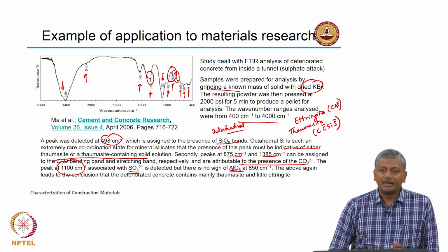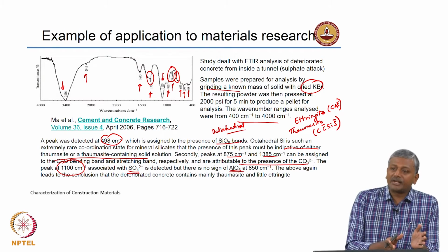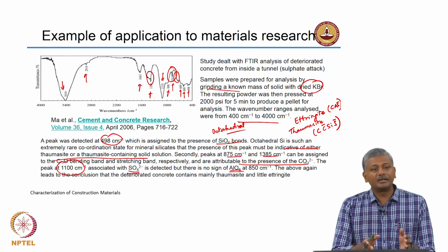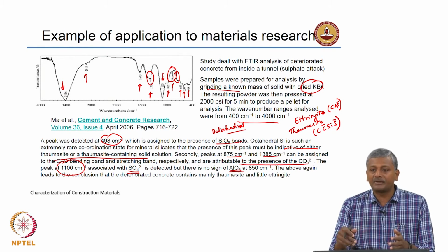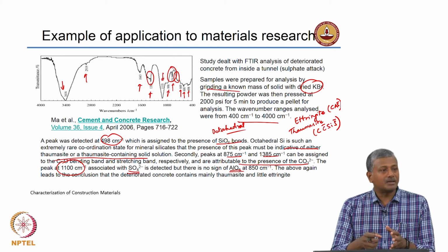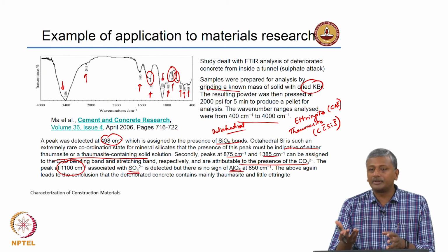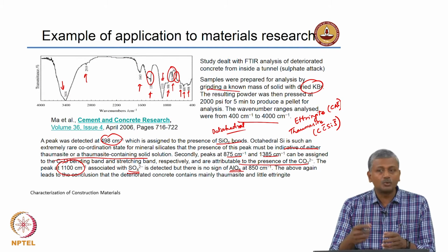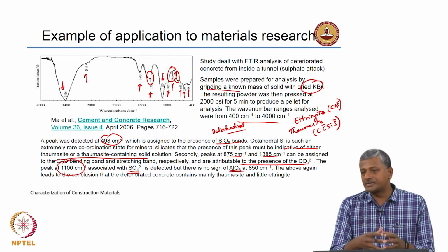Again, using X-ray diffraction in this case would have proven to be a difficult proposition, because most of the peaks of ettringite and thaumasite are almost at the same location. So, you have to choose your techniques carefully to understand the kind of detections that you want to do, and what you really want to prove as a result.